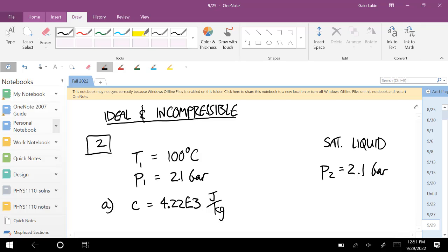And we have C sub P, that's the partial of the enthalpy with respect to temperature, holding pressure constant. For incompressibles, they're both equal to the total derivative dU/dT, and they're equal to each other. So there's just one value you have to look up. For gases, there are different ones.